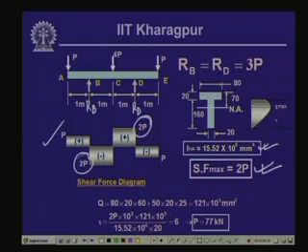Now, as we have seen, in the case of rectangular sections we get maximum shear stress at the neutral axis. For this rectangular component, at this particular section our shearing stress is not 0, but you will have some value which we call tau minimum, because you have some area for which you get the Q value, which is A y bar. When we took the rectangular section, above the top surface we did not have anything, and that was the 0 shear stress. Here, when we are considering the T sections or the I sections, above the web we have the flange area which is contributing to the first moment of area Q, but we are calculating the shearing stress from the interface and downward.